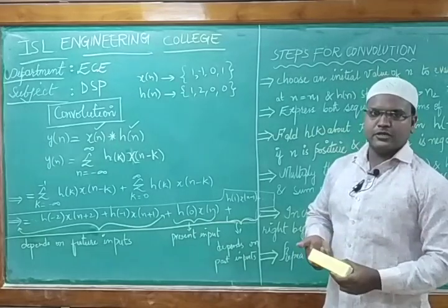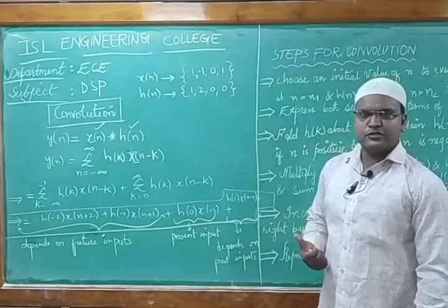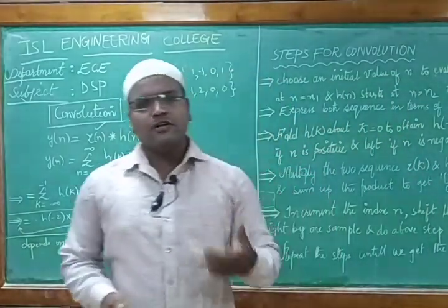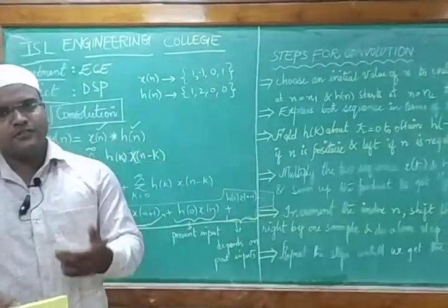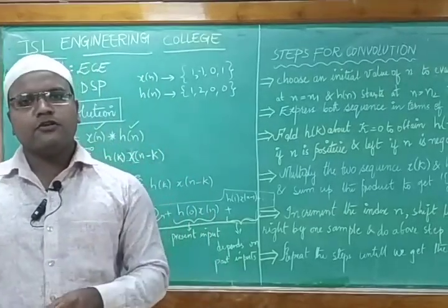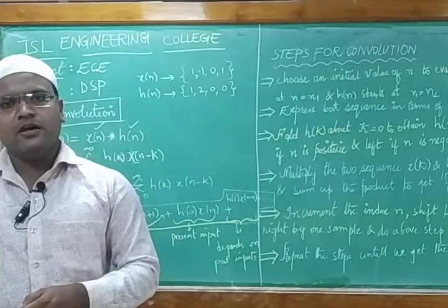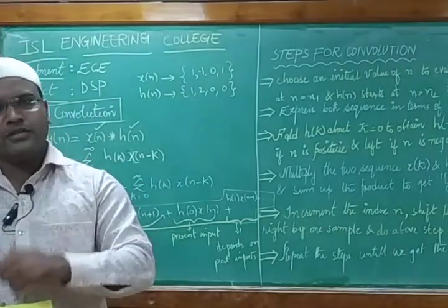called convolution. So in convolution we have two types: one is the linear convolution, the second is the circular convolution. What is the meaning of linear convolution? What is circular convolution? The first thing we are discussing is linear convolution. To do linear convolution, first of all we should know what methods we apply in order to get the signals convolved. So signals get multiplied or signals get delayed.